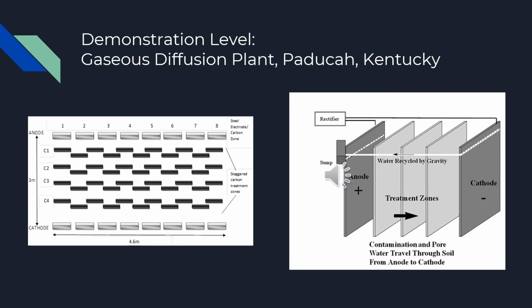The soil at this site has very low permeability, and the contaminant involved was TCE, which is trichloroethylene. The field test work started in January 1995 and ended only in May 1995. The field experiment served as a pilot study to see the electrokinetic effects.